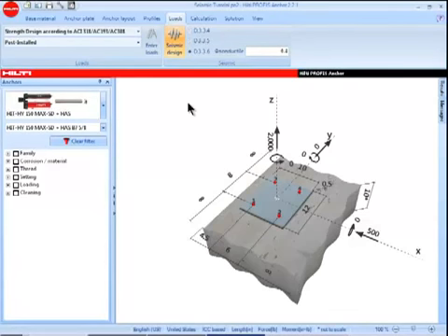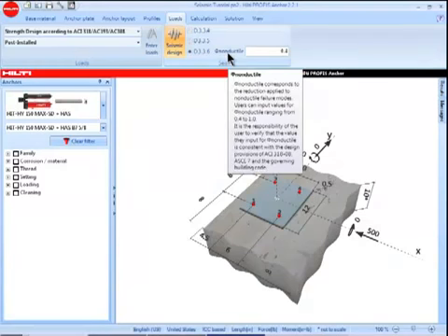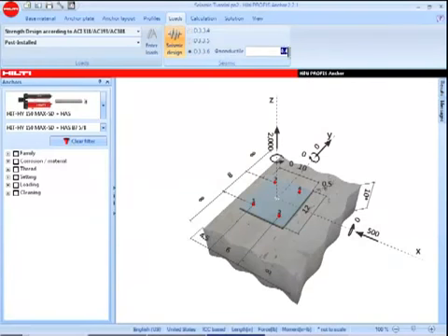A reduction factor will be applied to the calculated design strengths for all non-ductile failure modes in both tension and shear. This reduction is applied to all non-steel design strengths as well as to steel design strengths corresponding to anchor elements that are by definition non-ductile. PROFIS Anchor designates the reduction factor that is applied as phi non-ductile. Users can input values for phi non-ductile ranging from the default value of 0.4, which is given in ACI 318, to any value up to and including 1.